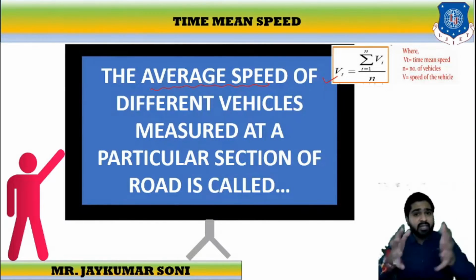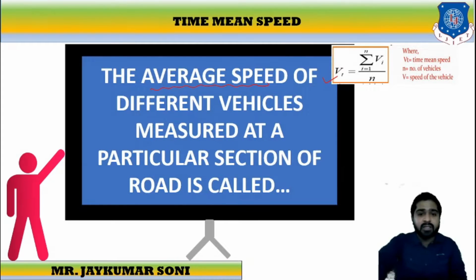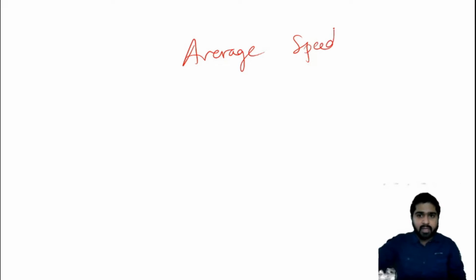Now let us understand this concept once again. I will repeat the definition: the time mean speed is the average speed of different vehicles measured at a particular section. So how can one remember it? First, it is the average speed. Then, it is of different vehicles.